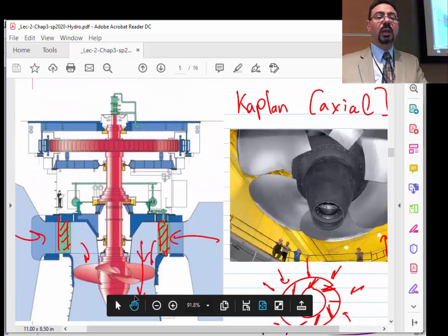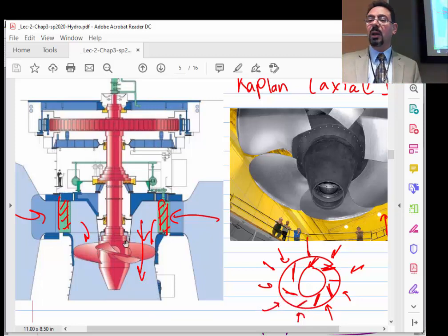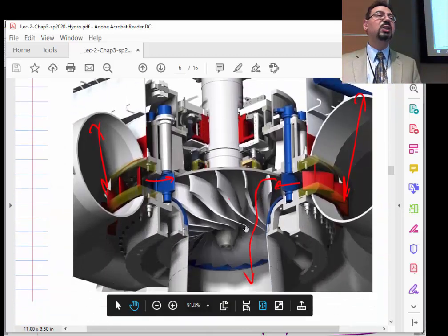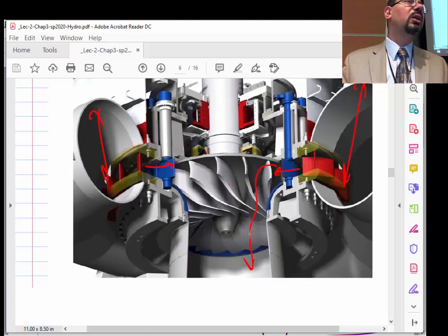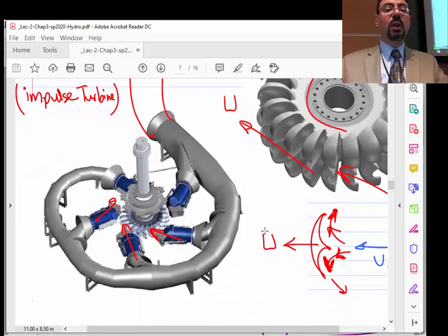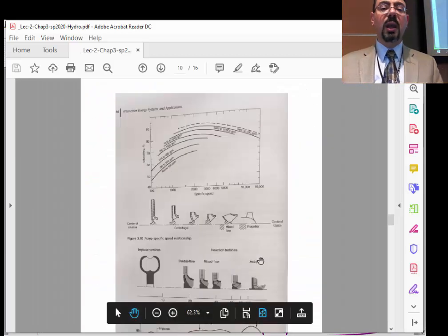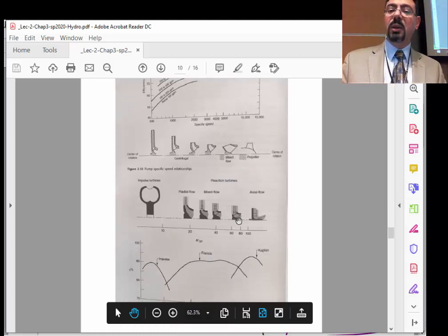And just one look at here, you can tell why it's higher flow rate. I mean, the space is open. A whole lot of flow can go through, right? Compared to that tight space. So in general, radial machines are higher head, smaller flow rate, and axial machines have higher flow rate and smaller head. Make sense? And if it doesn't make sense, all you have to do is calculate the specific speed and go to this graph, and you will land in the right place. Okay?